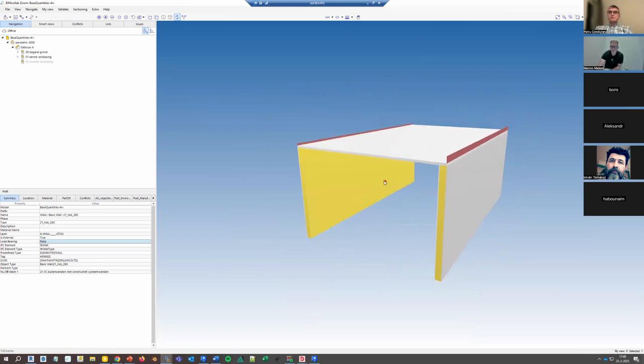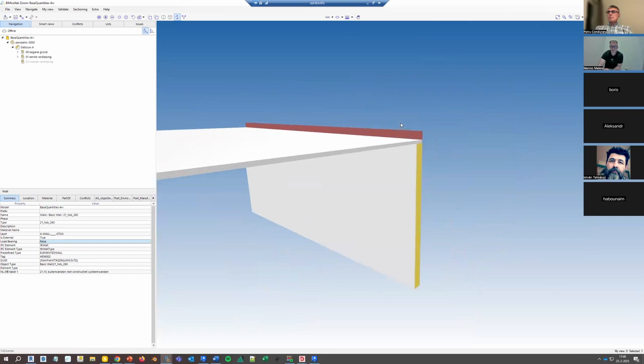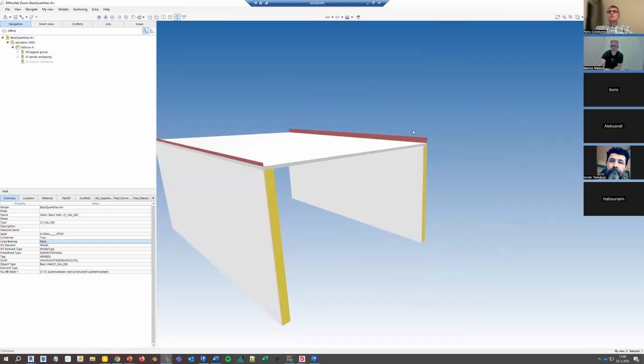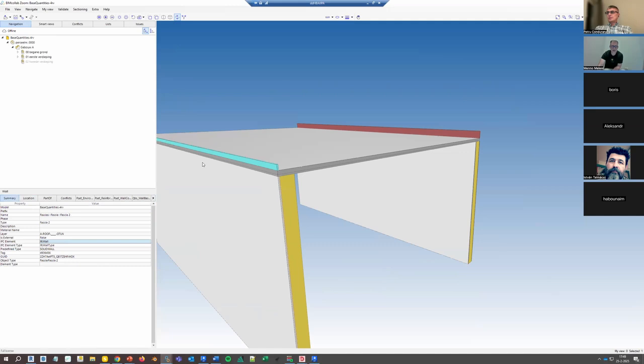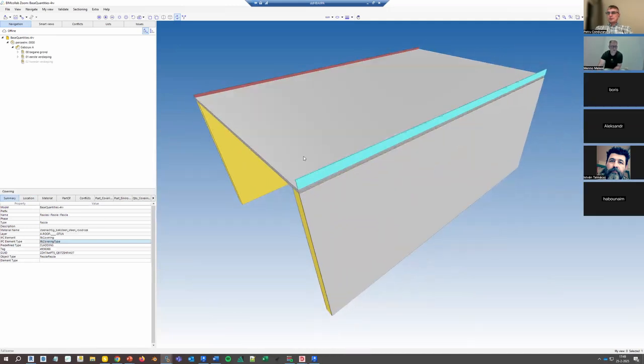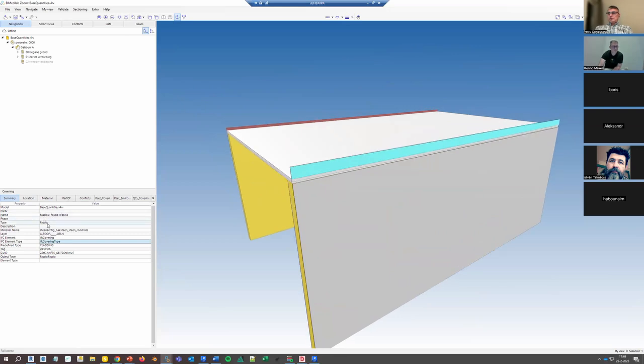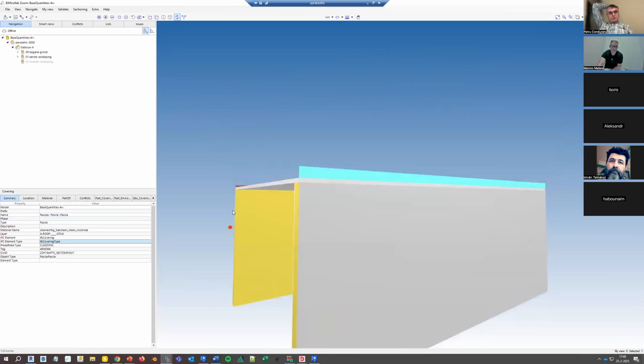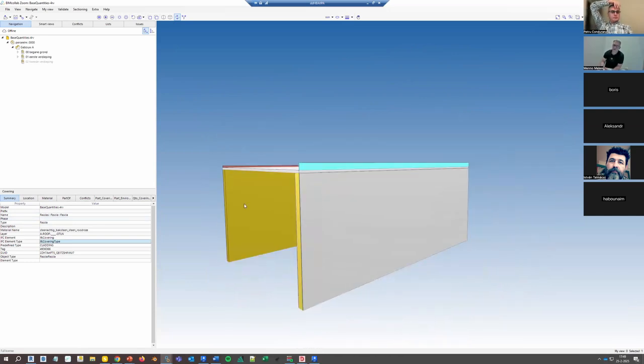But in a previous version, something that at first I was like, oh, that's nice. This one I exported as a wall, and this little part as a covering. But what you can see here is that it was a fascia. I never used it because it never used to export correctly to IFC. It always stayed an element proxy. But now apparently it's possible to export fascias to the correct entity, which is great.